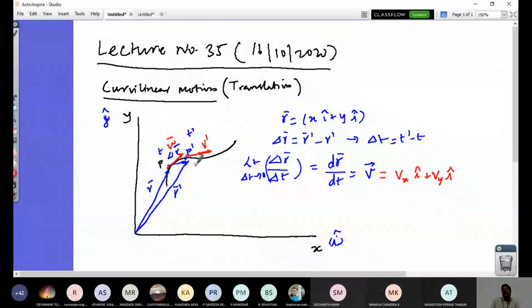Unlike constant velocity motion in a rectilinear case, which is not an accelerated motion, as we have seen, that is a static condition. But for a particle or rigid body executing its motion in a curved path, if the velocity is constant, you cannot conclude that it is not accelerated. That is accelerated. That acceleration component is the normal component of acceleration. We will see it in a while. That is necessary to maintain the motion along the path. So this is how I represent my velocities.